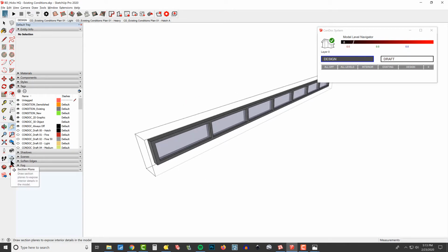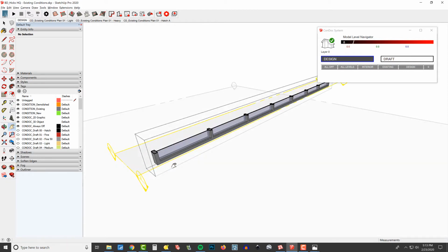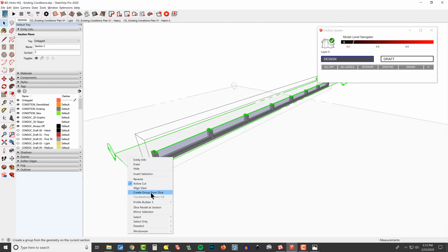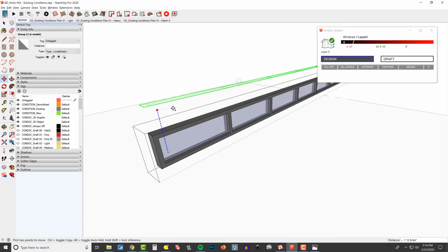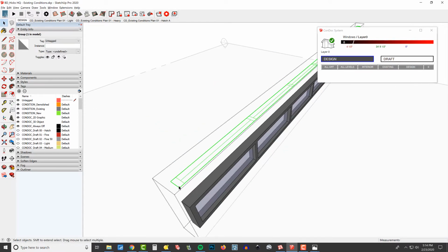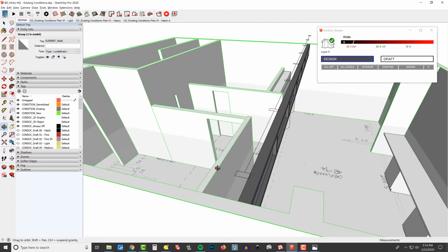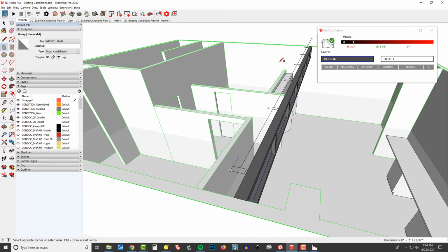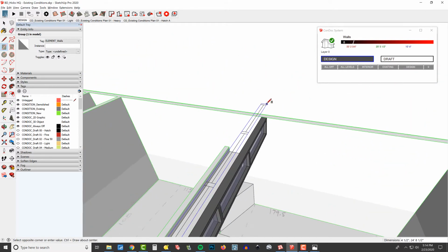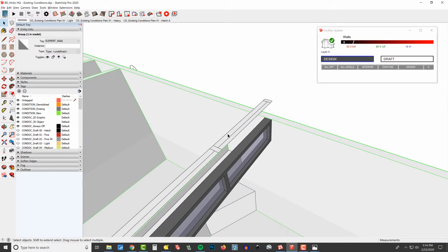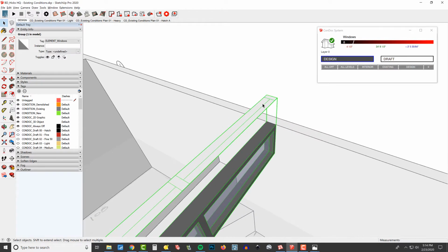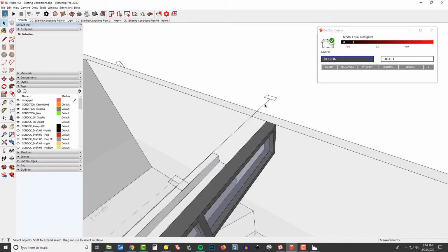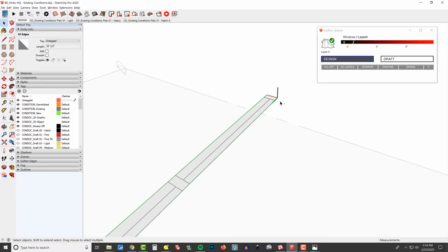and to make that 2D graphic, watch this trick. I'm just going to throw a section plane here, and then I'm going to right click on it and hit create group from slice, and then I'm going to delete my section plane, and then I'm just going to scoot this up above it, and let's take a look at this. I suppose I'll just complete the gesture here, and then I'm going to triple click. Actually, I put that in the wrong place. I'm going to cut this and get into this group from slice.